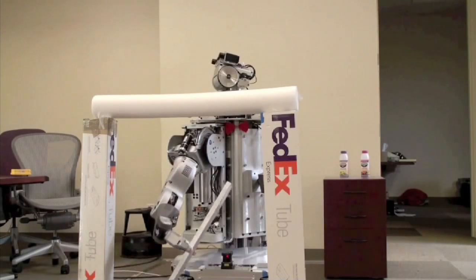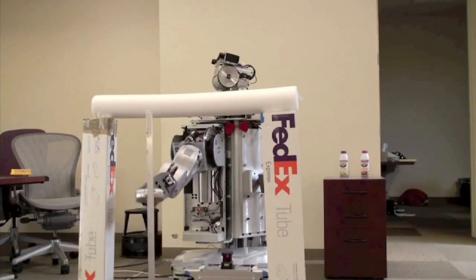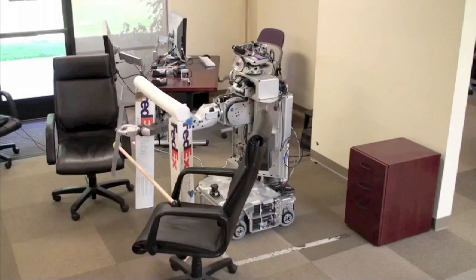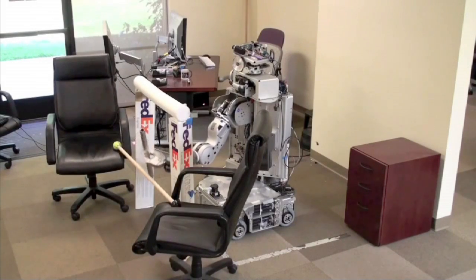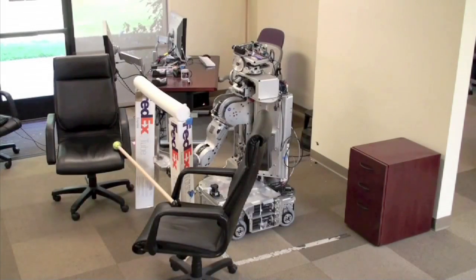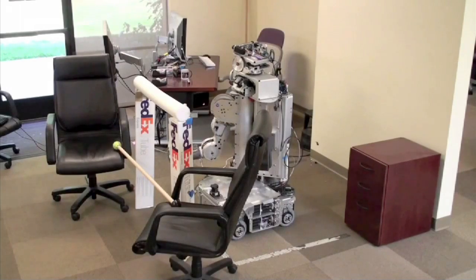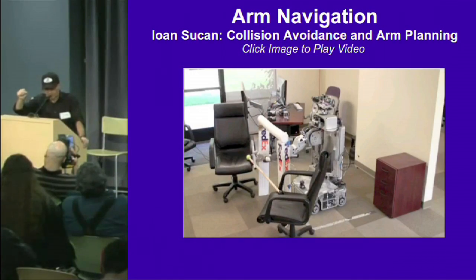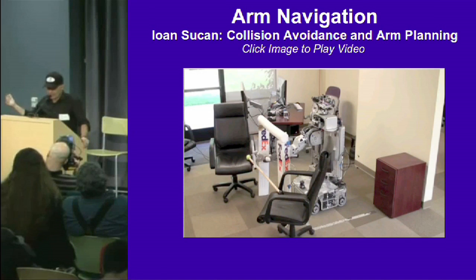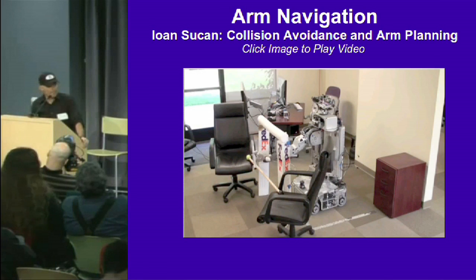In fact, I was thinking about this the other day. Think about when you're using a screwdriver to screw in a screw. You almost instantly project your sense of tactile sensation to the end of the screwdriver. Our brains are just automatically able to incorporate a device, in this case a screwdriver, into the joint map that is your arm. You have no trouble doing that. Well, the TF library does exactly the same thing. So once you put something in the robot's hand, you can immediately just add that as another joint dynamically on the fly, and nothing more needs to be done.